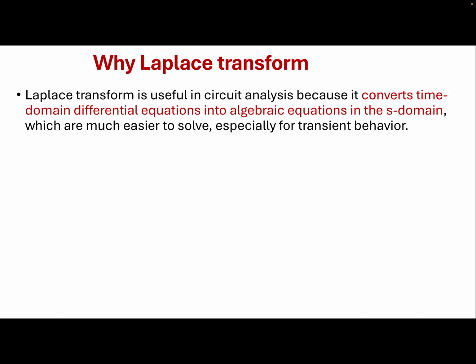I already very briefly talked about this: when we were solving a lot of these RC, RL, RLC circuits, we were getting first order and second order differential equations. What we are going to realize in this chapter is that if I take a Laplace transform of those time domain differential equations and convert them into the S domain, my operations will become super simple.